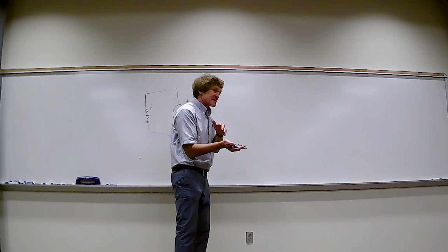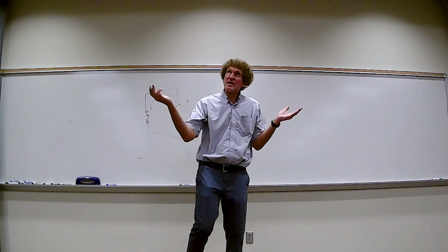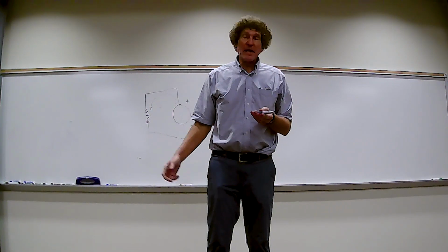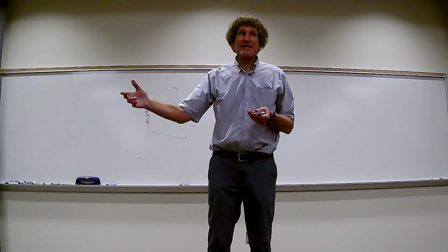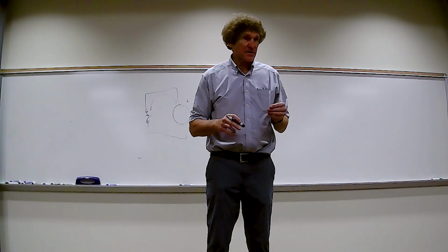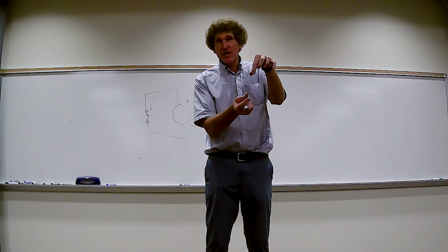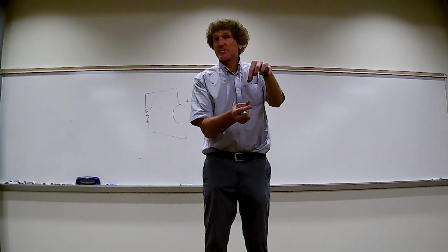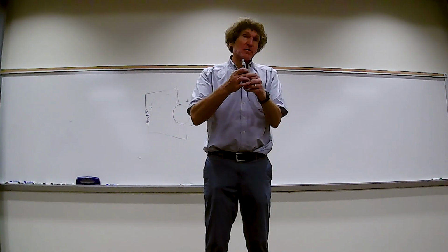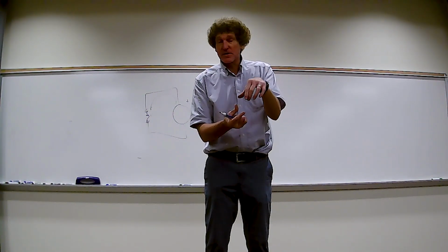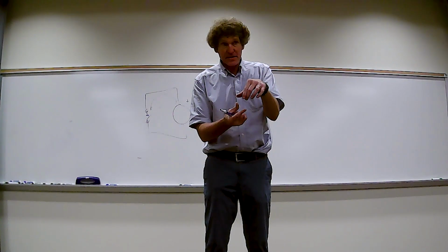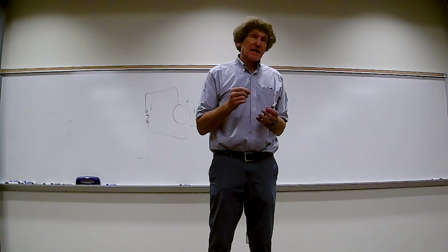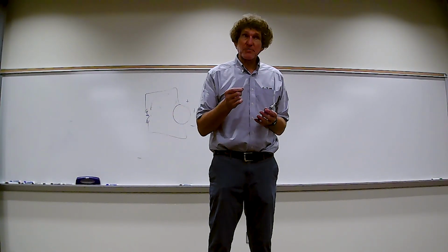Well, 60 hertz is, might as well just mention this, everywhere. Right? Our wall output is 60 hertz, right? Anytime you get current flowing at 60 hertz, it causes magnetic fields to vary at 60 hertz. So when you have a small circuit, and you have a closed loop around a closed path, that current will create a B field that will induce a voltage that you can calculate. You can calculate these things very easily. And when you get close to that wall where the currents are flowing, it can be very large and can cause all sorts of problems.